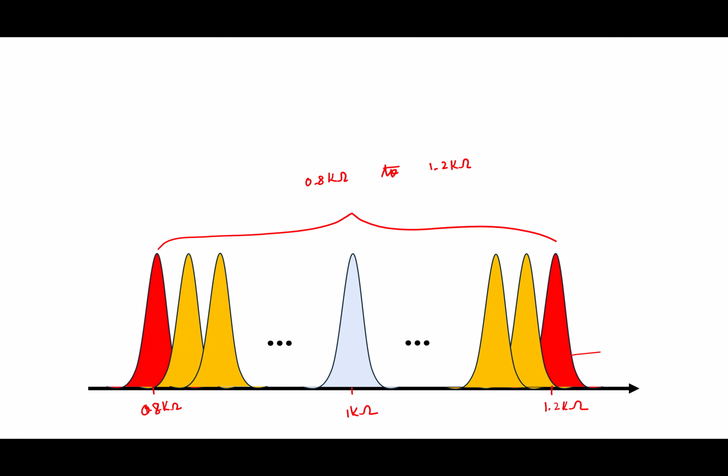So this variation in the mean value is what we call process variation. Process variation, in a way, is the variation from chip to chip within a single wafer. Now in a single chip, you have variation in the resistance values also. That is what we call random mismatch. That's just the terminology that we use. So variation in the mean is called process, and around that mean, whatever spread you have is termed as due to random mismatch.